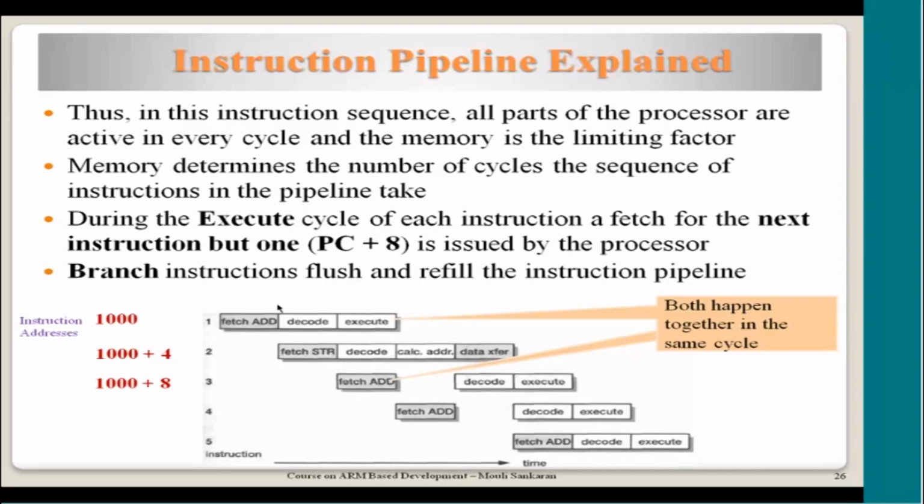And just to explain to you, if there is a branch instruction, we will talk about what it means. It means that the control flow is jumping to some other value. That means the branch instruction is modifying the value of R15. So it won't be the same as what is getting fetched here. After this execution, R15, that is the PC, will be loaded with a new value.